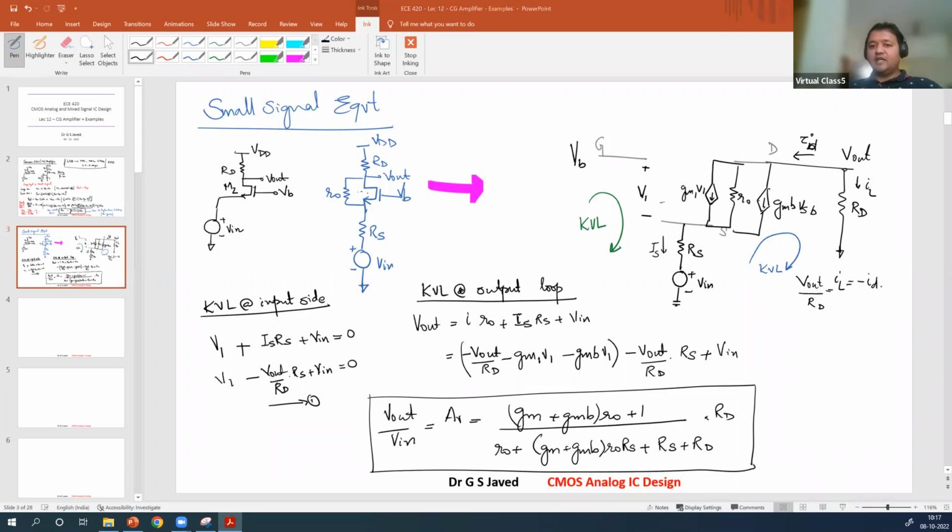So what do you infer from this circuit again? We infer that it is a non-inverting gain. Non-inverting gain, it has a gain larger than the CS stage. Okay, in this case, it is due to body effect. Right? Here, body effect is a desirable feature.